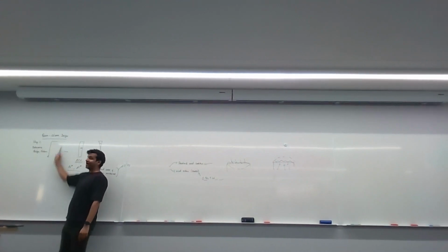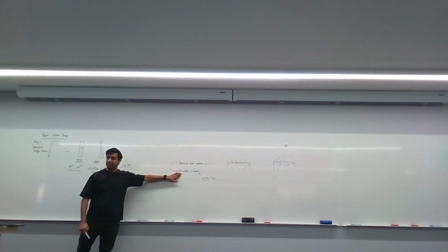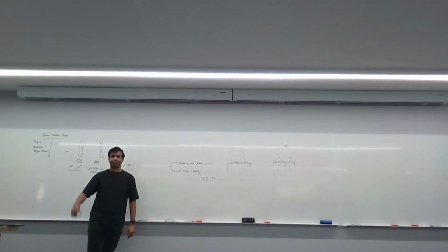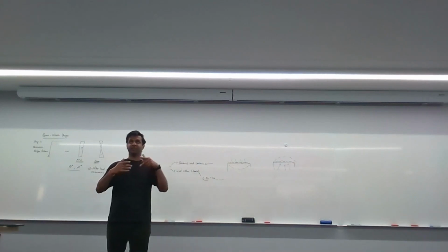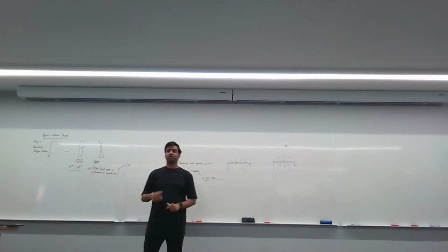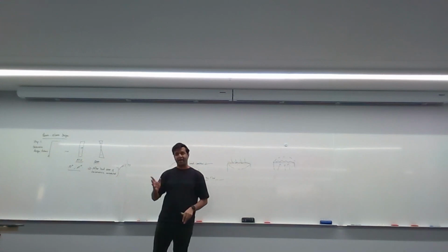If the wind is blowing upwards, using the wind action reversal combination, that might put my column into tension. It's entirely possible that your axial load is actually negative, which means it's going the other way, so it's in tension. Puts your column in combined bending and tension. That's entirely possible. It's rare, but it's possible.